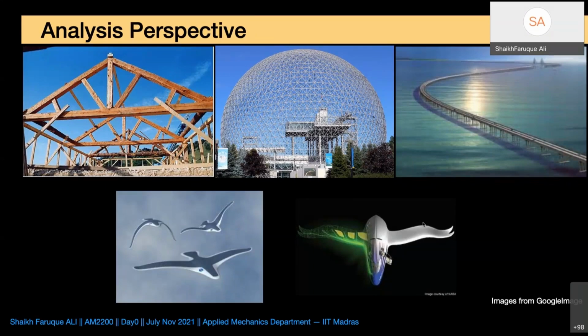Here are a few analytical perspectives. How do you analyze the structure? You need to analyze how loads are transferred. If you see this first picture of a wooden truss, the load that will come on the truss will be wind load, or maybe snow load, or maybe dead load from the top of the roof, and how that load is being transferred to the ground. Because you have learned from your engineering mechanics that we transfer all loads that come to a structure to the ground, right?